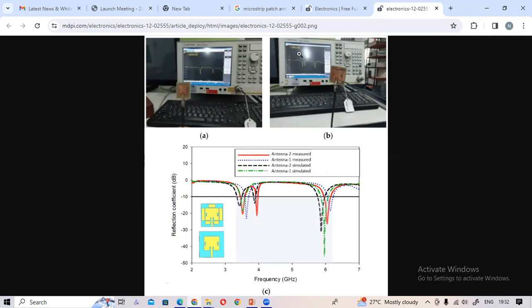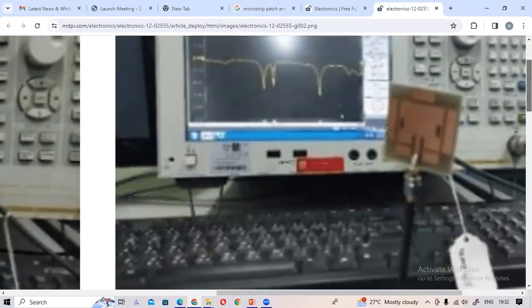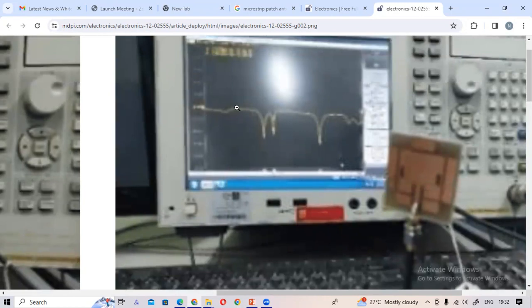This is a VNA, vector network analyzer. We have a nano network analyzer, and we have done one lab using that for the microwave instrument. So this is the S11 curve, the S11 curve for the antenna. In microstrip design also you have to find the S11 parameter. This curve you have to get in HFSS. So you have to learn what the S11 S parameters are.